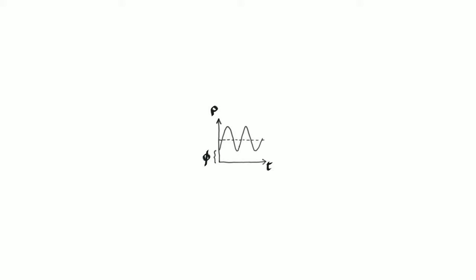What does checking the phase mean? In audio terminology, checking for phase coherence, or checking the phase, means making sure that all waveforms stemming from recorded instruments roughly have peaks, or nulls, at the same time so that sound does not cancel out. This is used after recording an instrument to make sure that the signals do not cancel each other. This typically could happen when recording drums with multiple microphones.